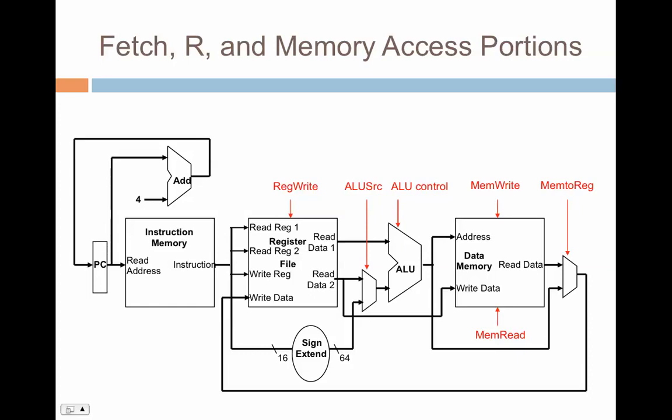For example, if you are thinking of an instruction like a load word, then you would need the instruction memory to load the word. You would access a register file to read the base value. You would compute the effective address. You access the data memory to read out the data and then write to the register file. This would be the longest instruction, and the time it would take would be the time for the entire instruction, which may or may not make use of all the functional units.